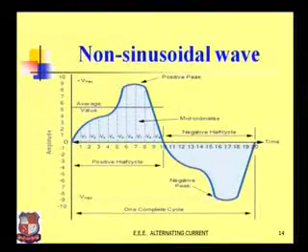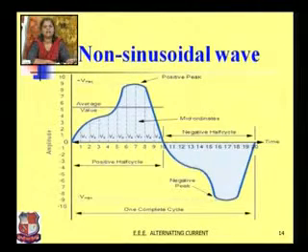So this is the mid-ordinate method for a non-sinusoidal waveform. Same way, divide your waveform into a number of parts. Here it is divided into 10 parts, and find the instantaneous value of voltage for each part, for n number of parts. The same way for positive, you can also apply it for the negative half cycle.